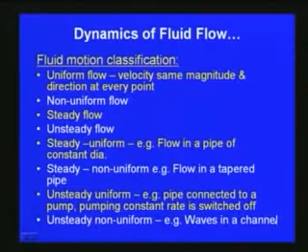And then we can also classify the unsteady flow as unsteady uniform flow. That means for example, a pipe connected to a pump, pumping at a constant rate, is switched off. So this is a case of unsteady uniform flow. Or we can have unsteady non-uniform flow, say for example waves in a channel.